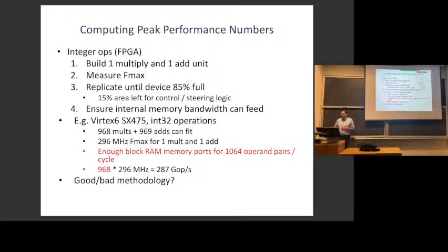Does that make sense? And also what they're comparing to is the CPUs and GPUs with basically all the data in the register file or L1 cache, which is also quite optimistic. You usually do not manage to fit all your data in the GPU register file and never have stalls, or always be in the L1 cache and never get stalls in the CPU. So in that sense, it's probably in line with what they're doing for other devices.